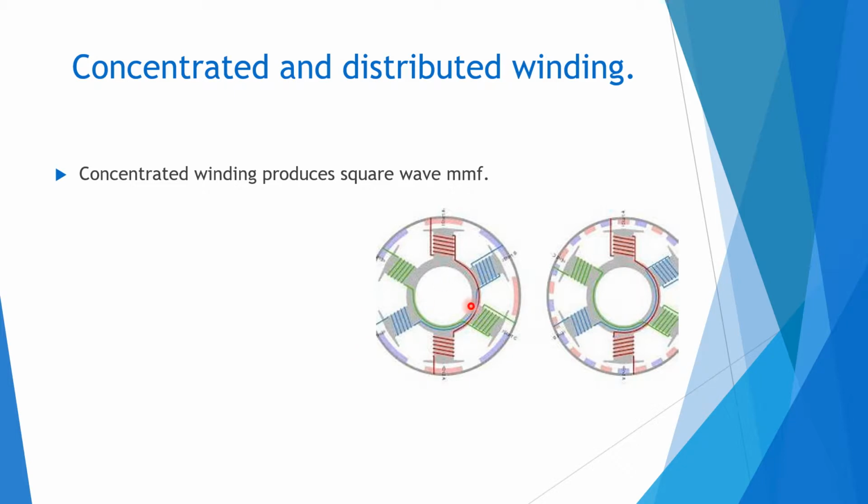There will be the whole air gap that exists here. We are assuming that there is no MMF drop in the whole of the magnetic material, so there is some MMF drop in here and some MMF drop in here. In a concentrated winding, these windings are not distributed over space; they are very finely pinpointed. There is current going in here and coming out of here.